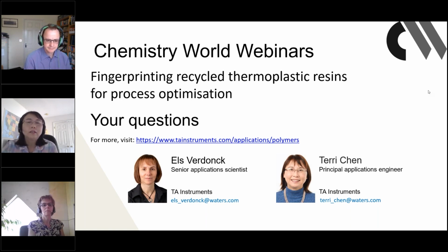This is a great question. Actually, to investigate a small amount of residue impurities, rheology is not that sensitive to do that. That actually belongs to using thermal techniques, like what Els just mentioned about using DSC and TGA. But for polymers which are a polymer blend system, yes, rheology, or more specifically a dynamic mechanical technique, is the way to differentiate whether or not we have an incompatible polymer blend in this recycled system.